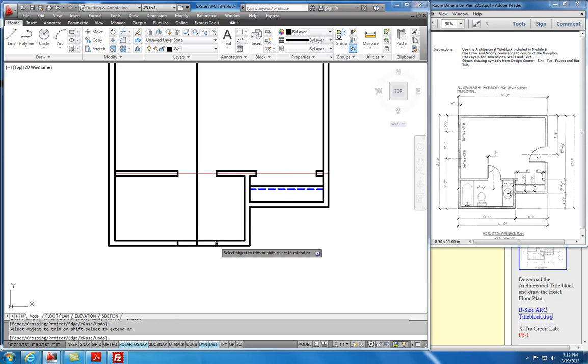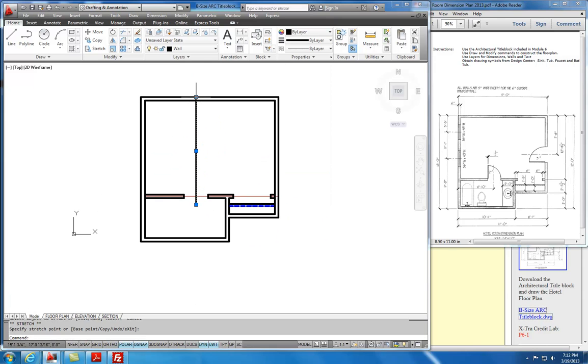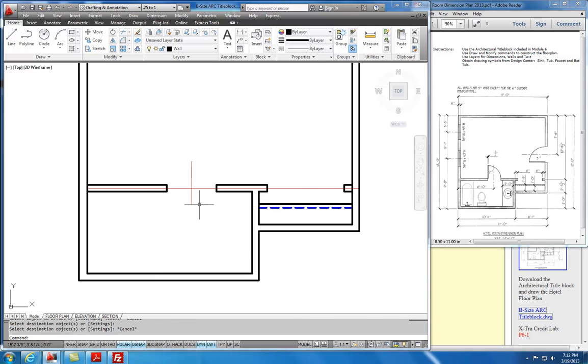And like I said, we can't trim these out. It won't do a 0 length. And so I'll click on them to select them, and then I will delete them. Okay, next thing that we're going to do is we are going to select this line. I'm going to just kind of bring this up a little bit, and I'm going to use that center line like I talked about, to match the properties. And so I'm going to say match properties. I want this to be the original look, and I want this one to look like that. And so I'll match that property with that line.